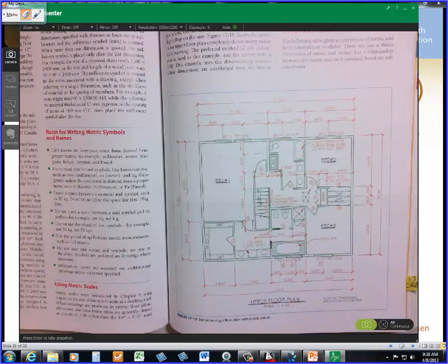We still have to keep the same text height. What's our text height in inches, folks? What's our standard text height? Come on. Bound to know it. 6 inches. No, well, 6 inches in scale, but on the finished plan, what are we after? Thomas, you know what that is? Text height?